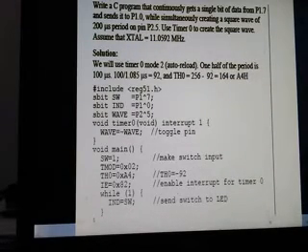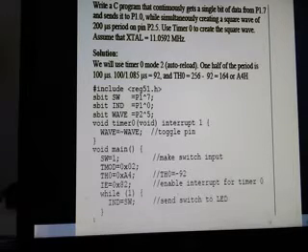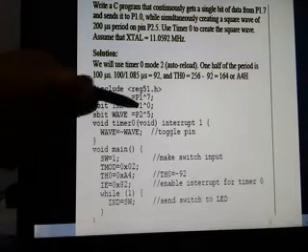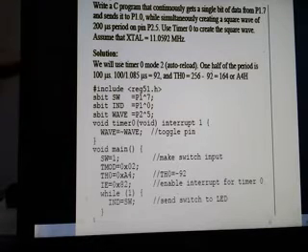Now C programming, first step, include the library file. Hash include reg51.h. Okay, then we will be requiring a variable to take the data from P1.7 and put it to P1.0. Both of them are single bit variables. Declare them with the data type sbit. So sbit SW, that is the name of the variable, equal to P1.7. sbit IND equal to P1.0.